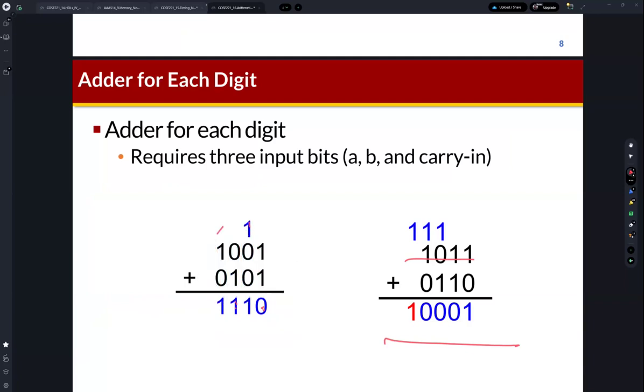So when we perform addition, in order to perform addition for the MSB, we need to know the carry in for the MSB. But in order to know the carry in of this MSB, we need to calculate this one, and this one. So what is the maximum delay? What is the critical path?